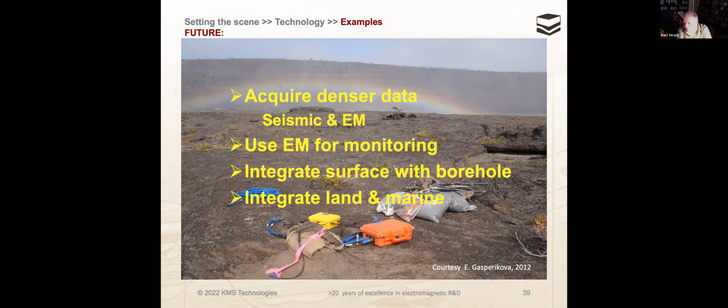But variations in the current is what you have to control in the data as well, in the source itself. So we have a current control in it, which is quite tricky. And we slow down the switching for this range. So we switch within 2 to 3 milliseconds. We can make it much faster, and then it would be for shallower targets. So we can modify that.